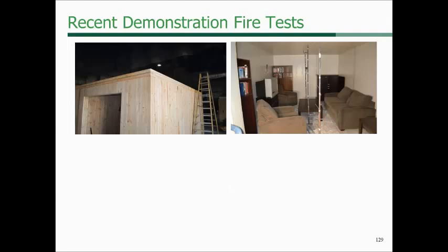It exposed two structures, one an entire structure of 5-ply cross-laminated timber, approximately 6 3/8 inch thick wood panel, with all 4 sides and the roof of this 5-ply. The second test was similar, with all the same walls, but used nail-laminated timber, all the same thickness, exposed to fire.